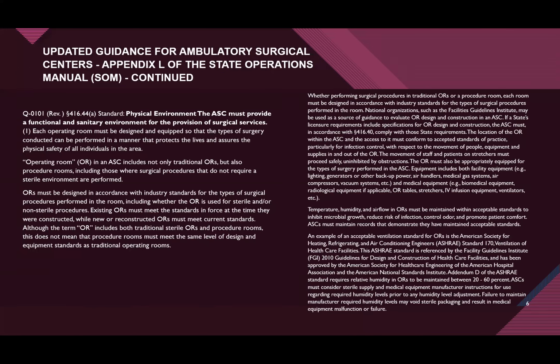The other thing that CMS says, and is a challenge to all of us, is the 20 to 30% humidity. In the beginning, CMS said all your rooms needed to be between 30 and 60. And the purpose of being between 30 and 60 was that there were no static shocks in the ORs, because we used to have flammable anesthetic agents.